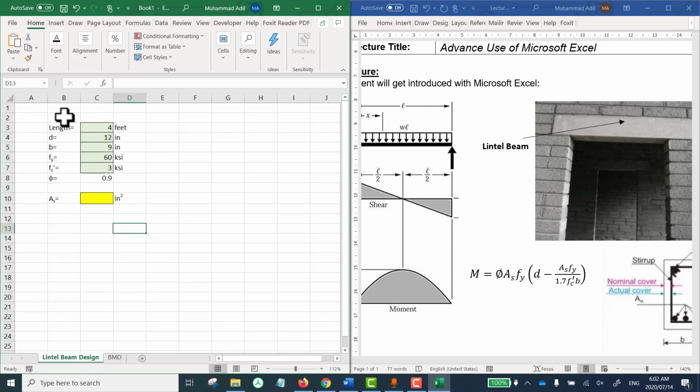Another thing we need to take as an input here is the load or W applied on top of it. So let it be W equal to the load here, and I'm dragging this up, so it will copy 4 for me there, but now I can change it to 1, and the unit is kip per feet.